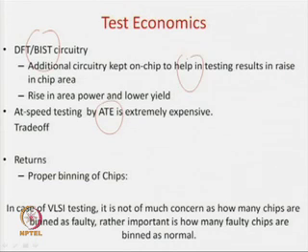My ATE is a third-party equipment, so I have to pay the ATE vendor. If I do some amount of testing with on-chip circuitry like BIST, or online testing, or some circuit I put on chip, then I can save some time or some amount of patterns in the ATE. But again I have to increase my chip area. So again there is a trade-off: whether I should pay the ATE vendor, or whether I put some extra circuitry on the chip for testing and make the chip size higher.